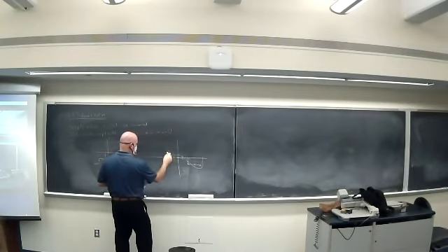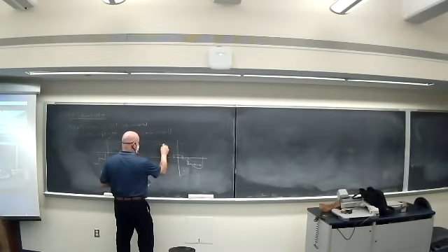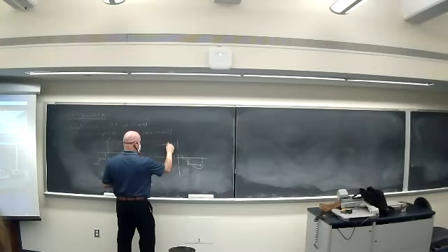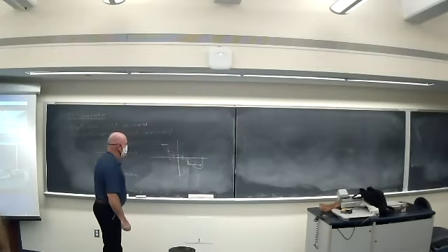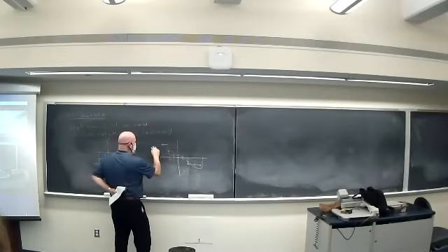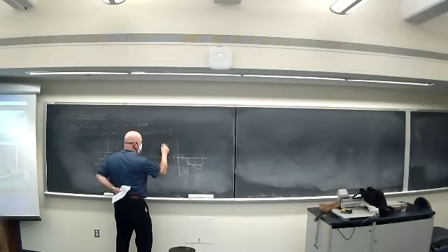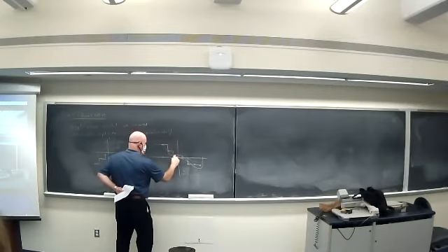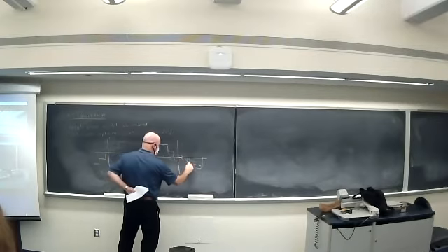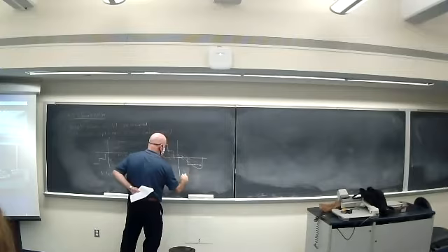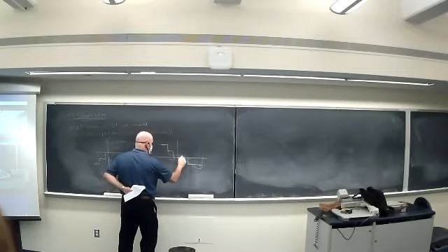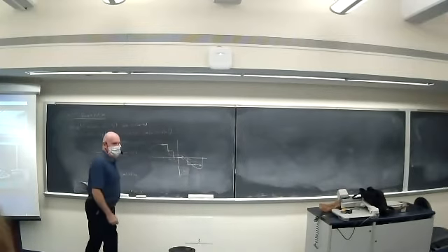And then back here, let me do a couple more. That one would be there, but then it would be rounded to 2, kind of at the same point. So our analog waveform is this continuous curve, but our quantized approximation to it, to 5 levels, is this stair-step looking thing. Okay.